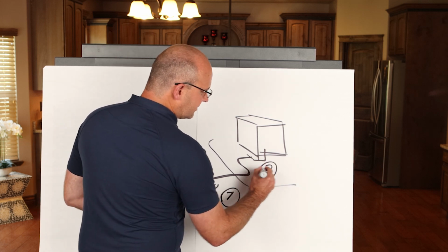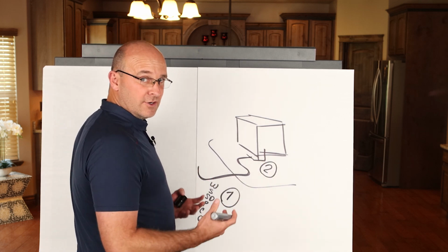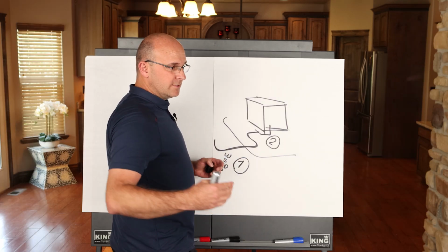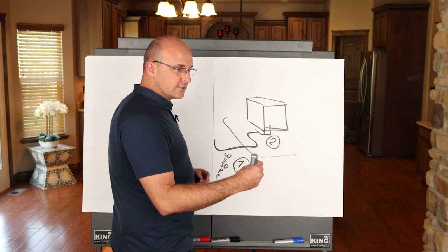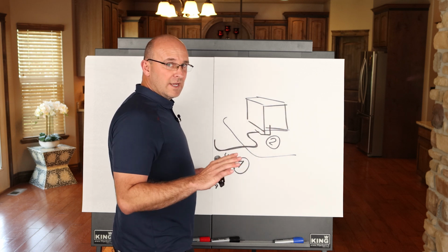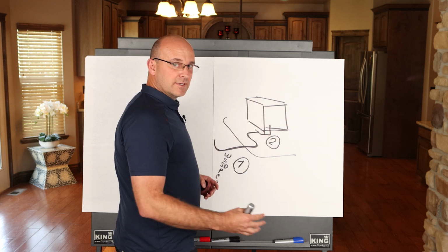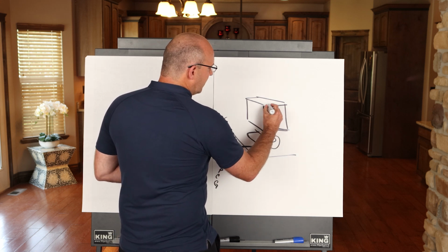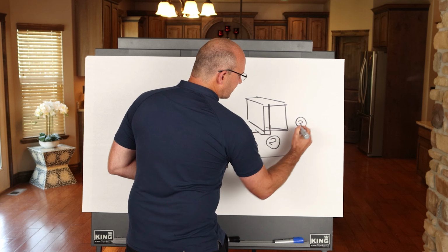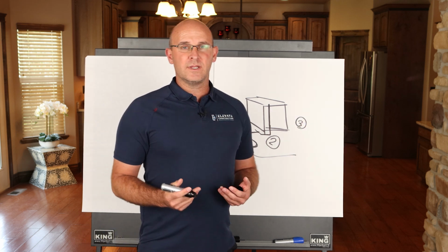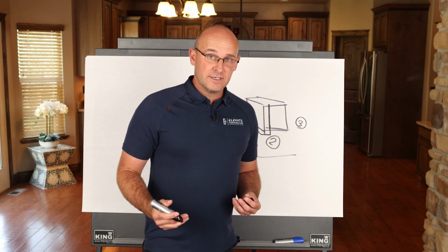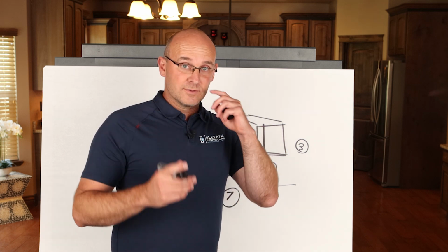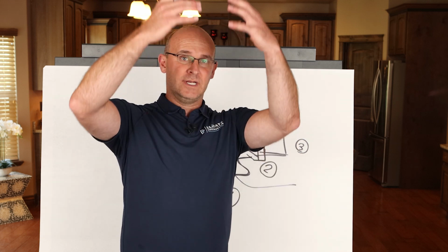Second step, the way I visualize it, is bringing it into your entry rooms, your ground level. That isn't always the case, right? Sometimes in different buildings, it'll come into a certain part of the parking garage or different locations. But in this example, typically ground floor, your entry rooms. Then you're going to want to come up the building. This is stage number 3. This is when you're coming up the electrical rooms, your independent distribution frames, your bathrooms, your chases, right? This is when most of what you need is coming up the building.